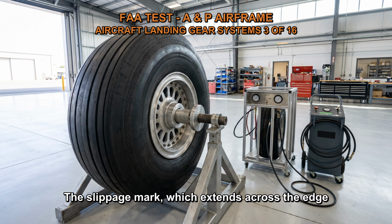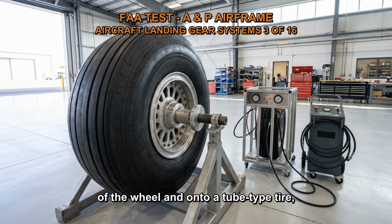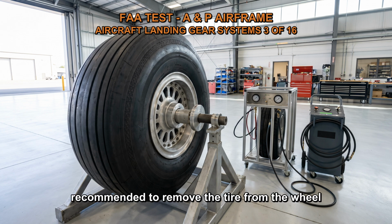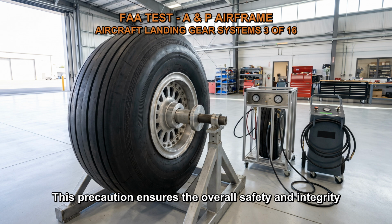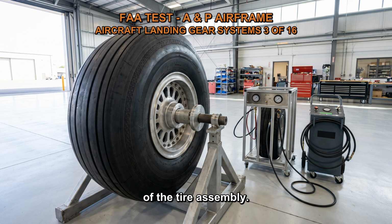The slippage mark, which extends across the edge of the wheel and onto a tube-type tire, serves as an indicator of whether the tire has slipped on the wheel. If the slippage mark appears broken, it is recommended to remove the tire from the wheel in order to inspect the tube for any potential damage to the valve. This precaution ensures the overall safety and integrity of the tire assembly.